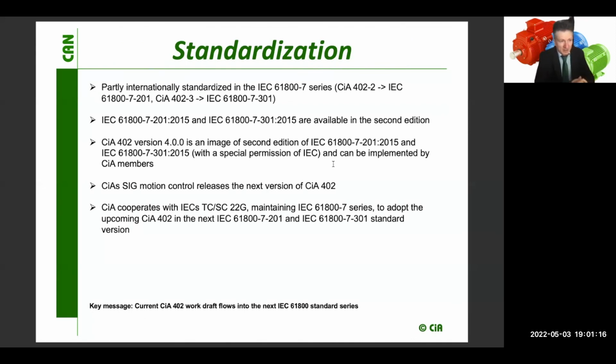Finally, having seen the application and how to handle things, we go to the standardization. The standard CiA 402 is standardized, not CANopen FD, not safety, but only the basic application parameters and PDO mapping for CANopen. It has already been released twice, 2 versions of the standard.